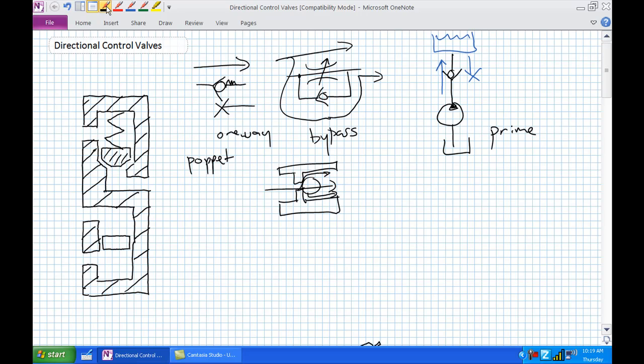But let's go ahead and modify this right angle check valve by putting a secondary chamber below it. The secondary chamber has a little piston that can move up and down, which wouldn't really be special until we connect these guys via a little rod that passes through here.